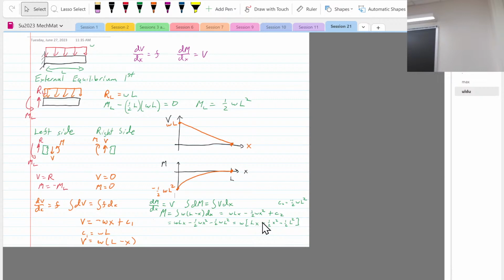So that one is contributing a bending moment, right? It's also a shear force too, I think. No, so PX, right, there's no x. If I were to move it over to here, it'd just be a normal axial force, right? So it's also contributing a normal stress in the x direction of PX divided by the cross-sectional area. So that is everything that PX contributes.